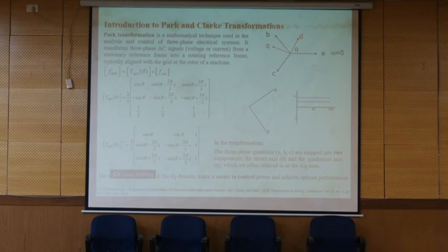It means that we just provide the reference from IL, and then split it to ILD and ILQ, and later we can see the ILQ will be reactive power and ILD will be active power. But it is not always like this. It depends on how you calculate it. You will see it. And then I ask the converter to provide the reactive power based on this reference. And based on this, we inject just ILQ, and ILD is coming from here.